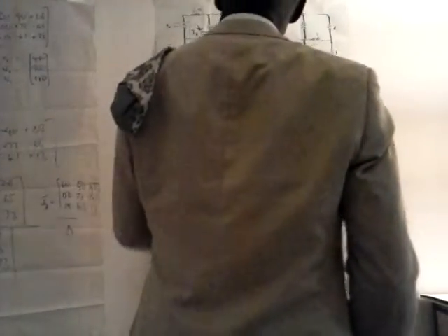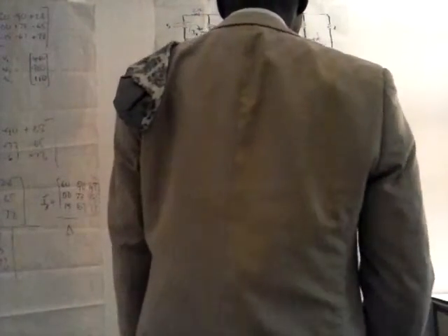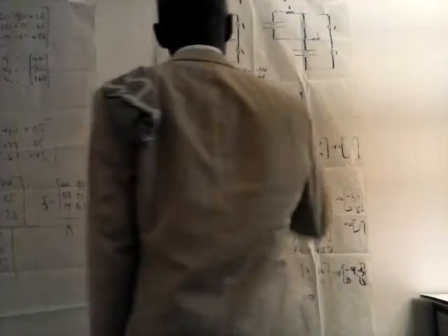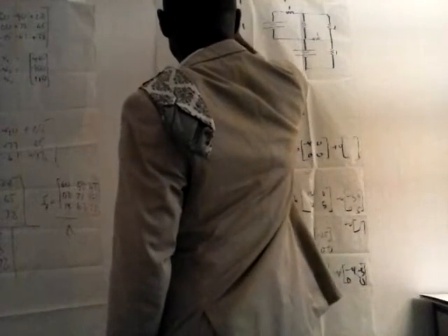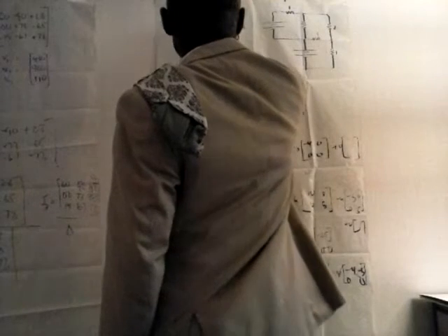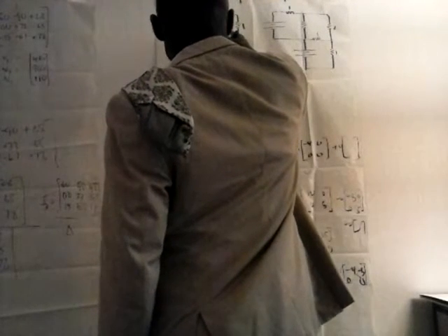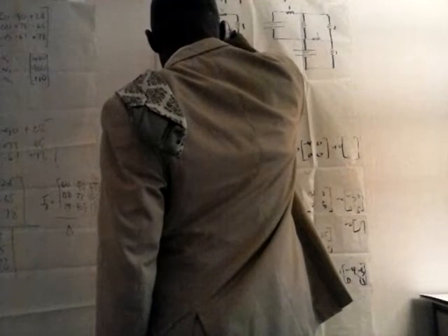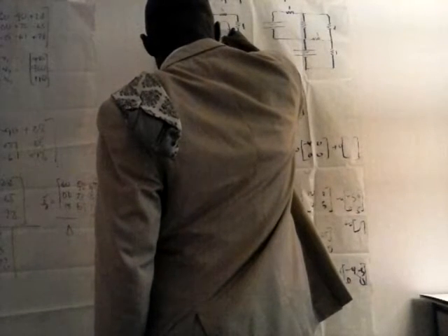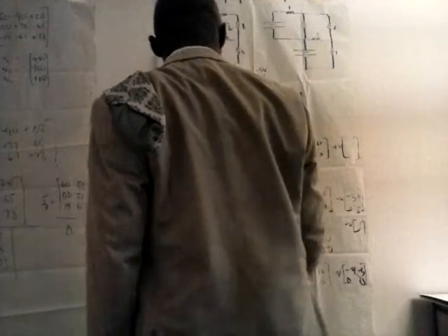So the only place we would have a current is in I2, which is 400 over delta. So in this circuit, the current here is 0, the current here is 0, and the current here is Ni2 over delta equals 400 over delta.